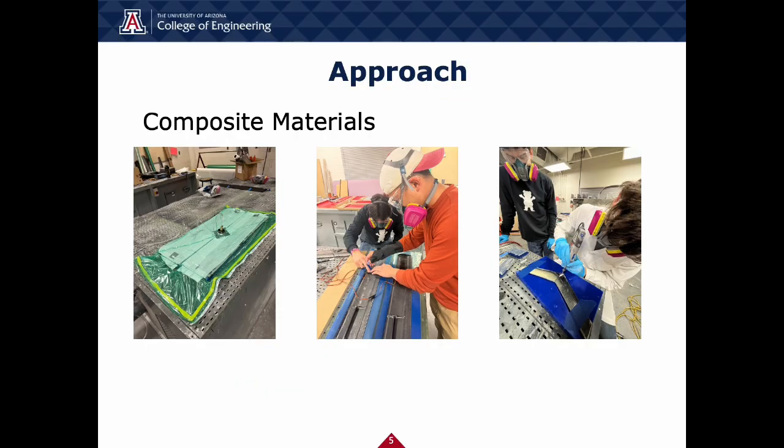Next, we used those molds to hand lay up carbon fiber structures for the wings and tail, and fiberglass structures for the nose cone and tail cone. This arduous process involved many hours of learning how to optimize layups, sanding excess material to form, and bonding composite structures together.